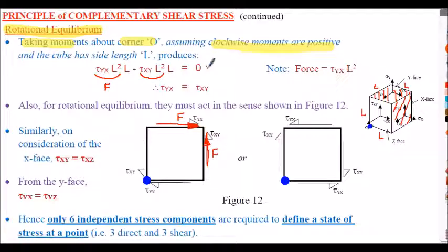So you can see clearly that all the L terms cancel. If I divide throughout by L cubed, then all the L terms cancel, rearranging the equation. The stress yx, shown here on the top, must then equal the stress xy on the side. So in other words, those two stresses have to be the same. I've labelled them as different in my initial considerations, but actually for equilibrium they have to be the same. Otherwise I won't get moment equilibrium for my little cube here.